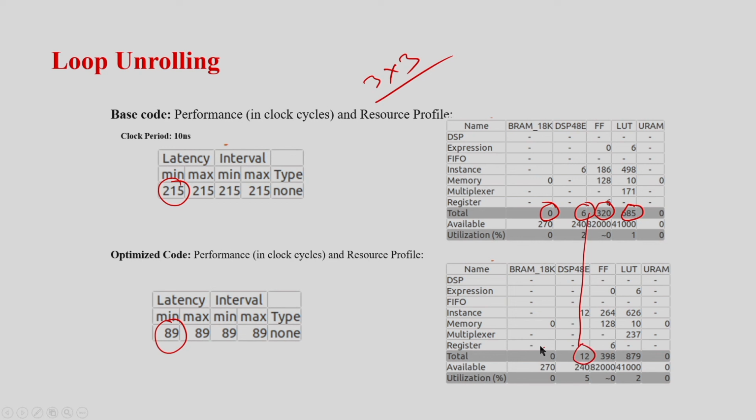So, you might say that now I unroll, that means all these operations are happening in parallel, so why is it not 3 times, because there are 3 multiplications going to happen, right. The answer is that the scheduler may not schedule everything in one cycle. Based on the combinational delay, it might decide to execute in, say, 2 cycles or whatever.